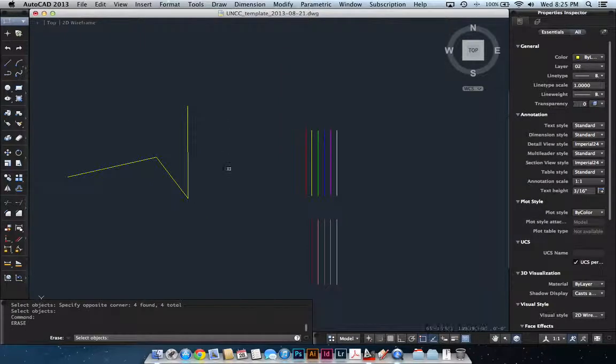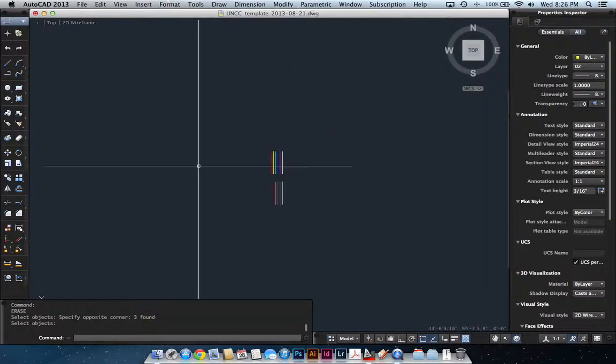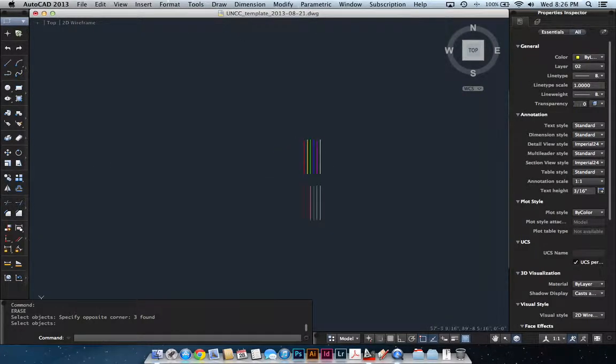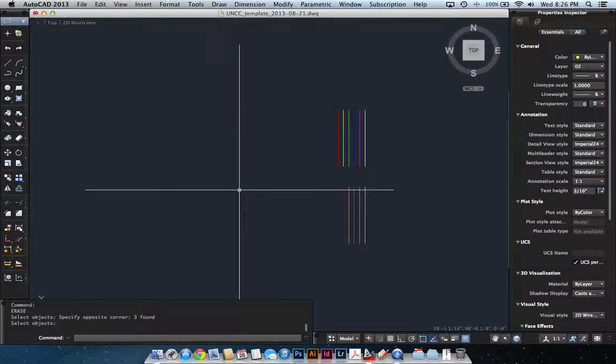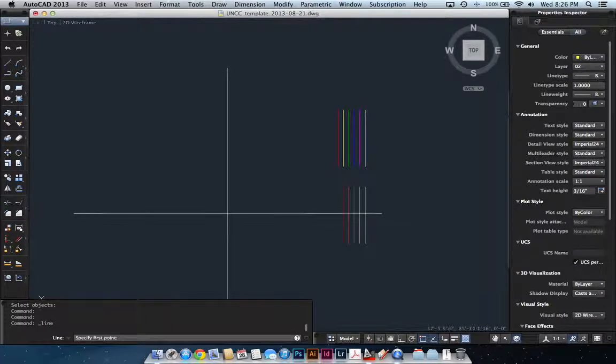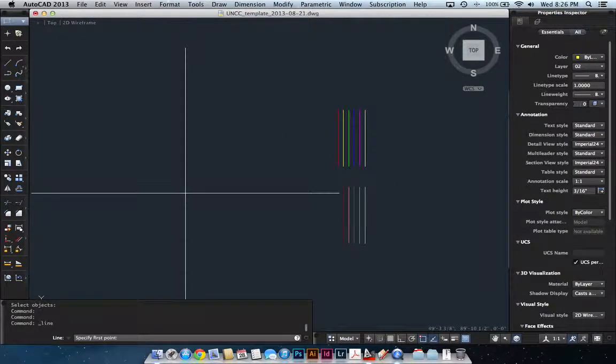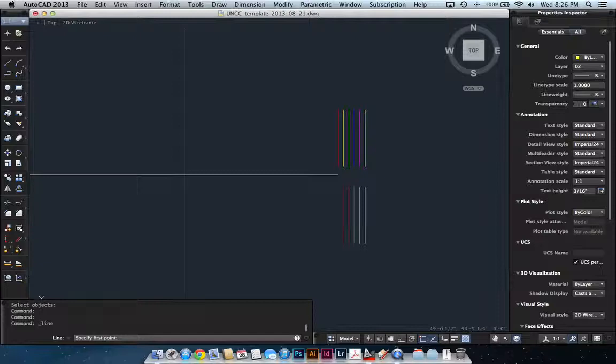and now we're going to go over the idea of how to show a dimension while you're actually in a command, like the line command. So by default, when you're not on the ortho, which is down here along the bottom toolbar, it's also Command L is the shortcut on the Mac, or I believe it's F8, Function 8 is the shortcut command on Windows.